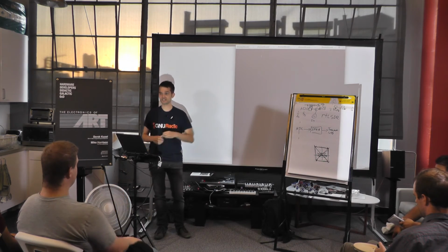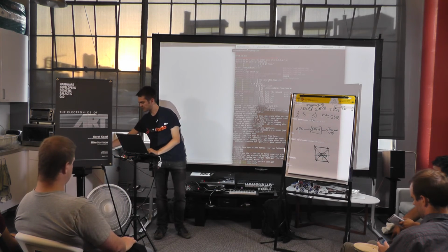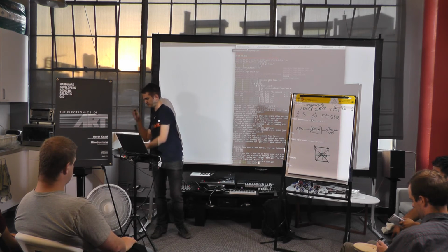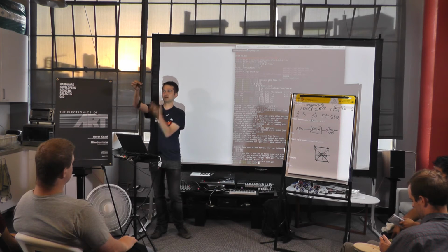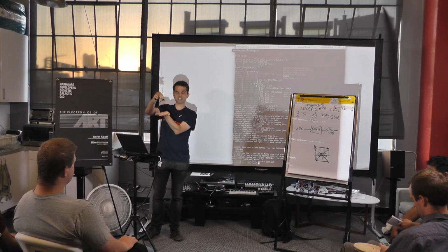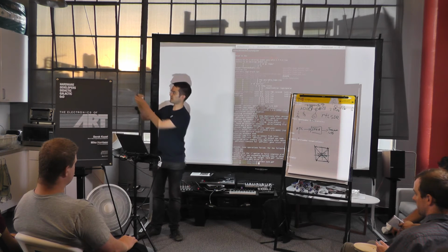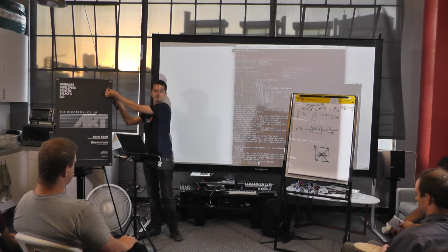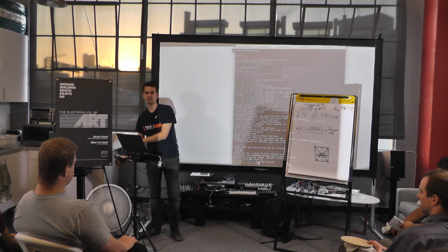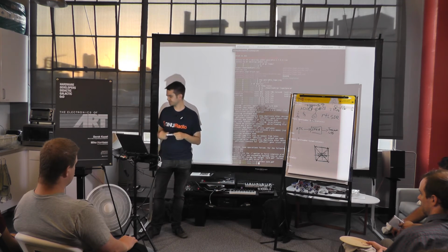So sorry, yes? What kind of antenna are you using? So right now, I am using a super cheap little dipole antenna that I can untangle. Looks a lot like this. Well, actually, it looks exactly like this because it is this. It's got a little magnetic mount on the bottom. This actually ends up only being half of an antenna. So if I were to just stick this on here, we'd get really terrible reception. So instead, I have it stuck to the bottom of this stand, which is metal. And the metal plane there is actually forming the other half of the antenna.